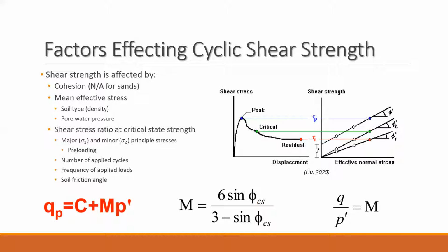Additionally, as seen from the depicted graph, a soil's peak shear strength isn't maintainable, so under increased loading, a soil's strength will constantly degrade until it reaches a stable residual strength. The same concept applies for cyclic loading, as when the strength of the soil reaches a level corresponding to zero effective vertical stress and large cyclic shear strains, the soil shear strength will decrease significantly and liquefy, posing significant risk to infrastructure.